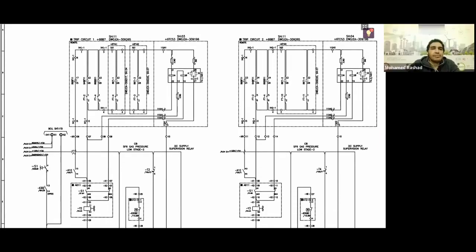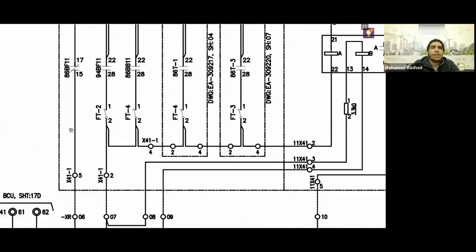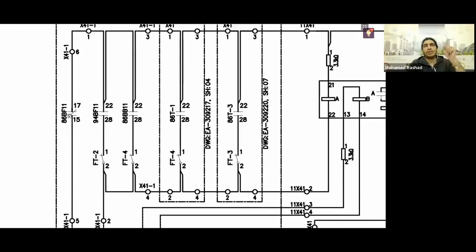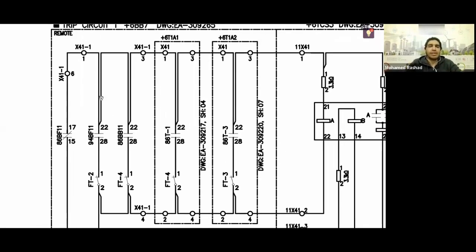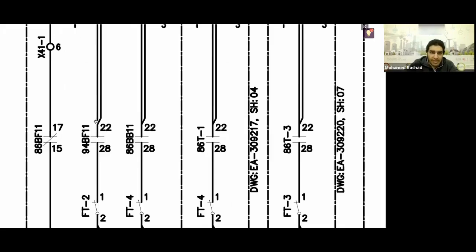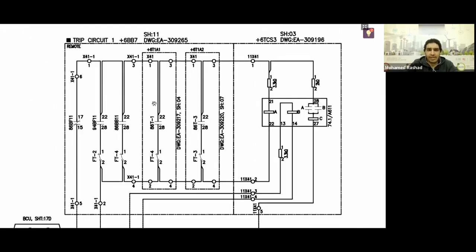All right, so you have the positive coming out here like this. The first thing it encounters is a normally closed contact from the breaker fail that I mentioned to you. Then it goes here and finds, for example, one from the trip relay, one from the lockout relay, and exits. Notice where it enters, it goes up to the coil contact and exits from the contact itself, and so on. We keep going in and out, in and out, until I reach a resistor.